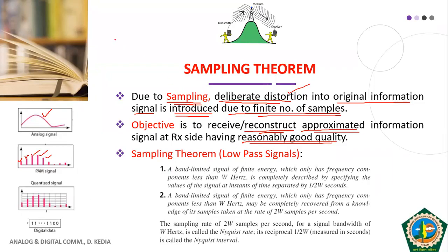See, what I want to say is that I had one analog signal with me, it had infinite samples. So instead of infinite samples, I chose certain sample values, say these 6 values. So by looking at these 6 values, I can easily make out that, okay, approximately my signal may be like this.